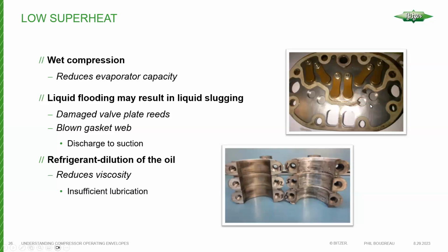And just a note about this, sometimes these webs will blow out because somebody's actually changed valve plates or gaskets but didn't correctly torque the heads down. There is a torque spec for every compressor. For example, the Bitzer CE4s, all of the conventional 4-cylinder and the conventional 6-cylinder, all use an M10 type metric bolt with a bolt quality of 10.9, and these should be torqued down to 80 Newton meters or 59, call it 60 foot-pounds. But it does depend on the bolt size, the quality, and the whole bit.